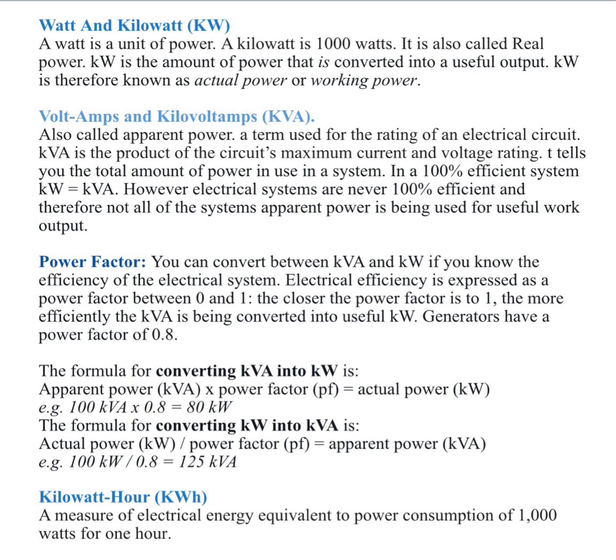But now to the battery system. Batteries are also rated in kilowatt hour: 5 kilowatt hour, 10 kilowatt hour. It means the amount of energy that the battery can dispense if you put a load on it. Let's assume you have a load of 1000 watts on an inverter and a battery of 5000 watt hours. Let's assume the depth of discharge is 100%. It means you can take the 5000 watts divided by the 1000 watts, which means you can use that battery for 5 hours.